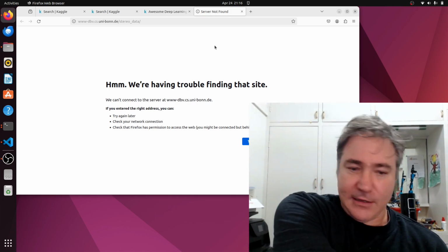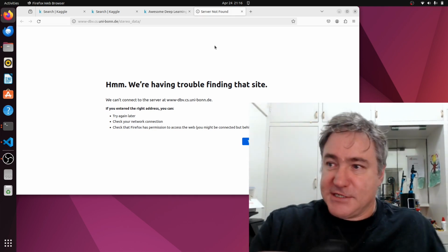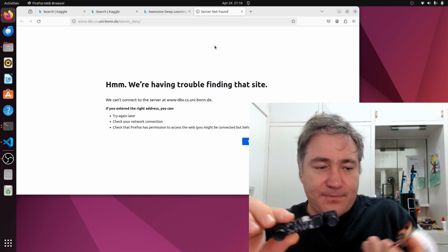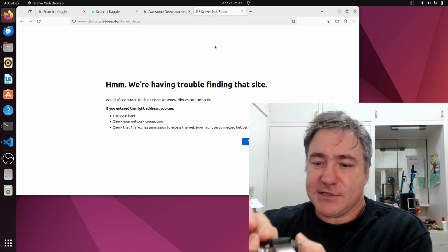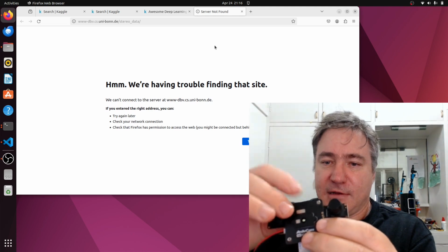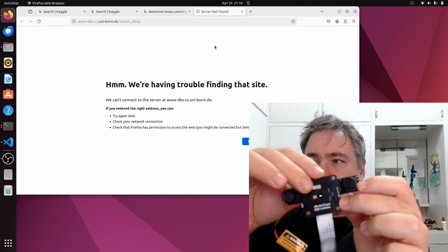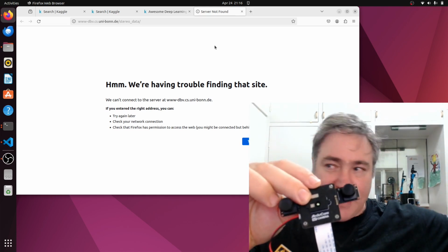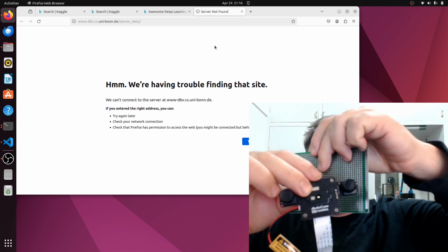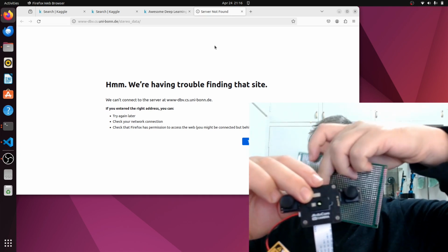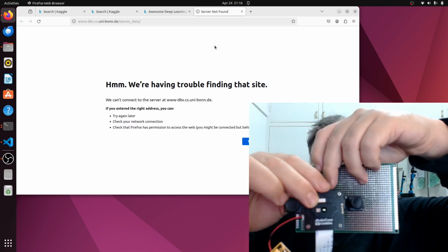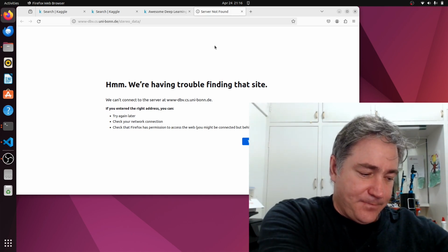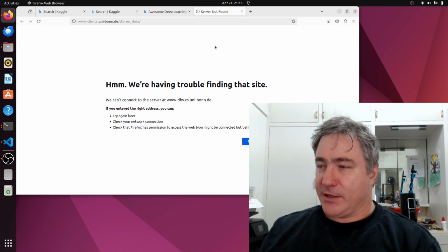So what I've got here is a stereo camera, and then this is a time of flight camera. So I'm going to put these two together like that, and then I'm going to be able to collect the stereo pair and the disparity image all together. Then I'm going to mount them onto this perf board just to keep them all aligned, because this has got a grid structure on it, so I can keep all the lenses aligned perfectly when I do that, and record my own data, and then I can use that to train my neural network.